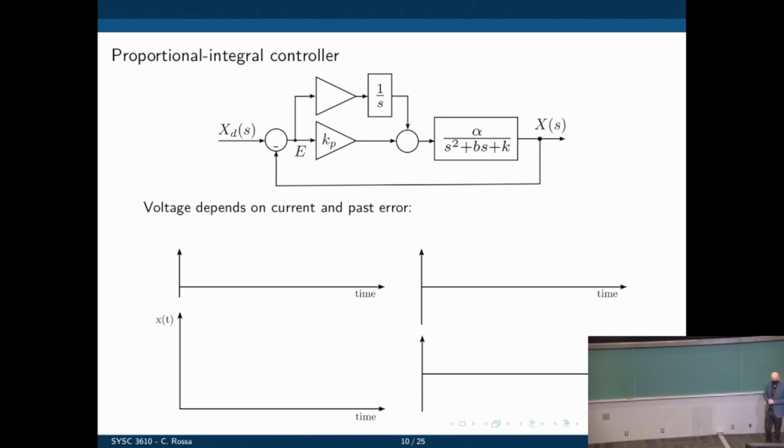So to eliminate the steady state error, that's where we use the integral component. Now let's add this top loop here, and let's add an integral gain. Now we have two components. Our voltage given to the motor is now a sum of its proportional error and integral error times Kp and Ki. That is up to us to find. So let's see what that does.